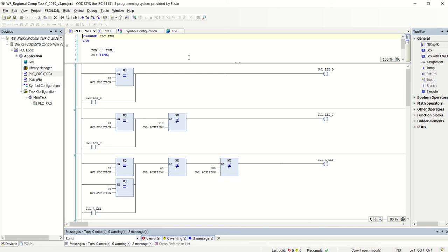So we looked at a method through OPC communication between Codesys and FluidSim for testing it, and that was quite nice. But there is a lot of downloading additional software packages, and license agreements that need to be done. So there is another way, where you can use the inbuilt visualization within Codesys. If you're developing a HMI, human machine interface screen, you would use this for simulation. It's quite nice because it's fairly intuitive, and it can help fault find some of our code here.